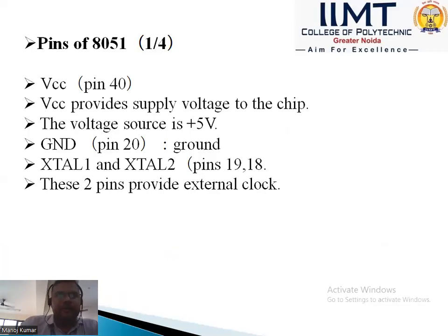Pins of the 8051. This is the VCC pin, pin 40. VCC provides supply voltage to the chip. The voltage source is 5 volts. This is the ground pin, pin 20. This is XTAL1 and XTAL2, pins 19 and 18. These two pins provide the external clock.